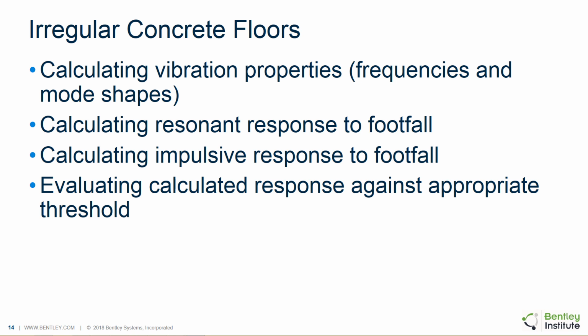And typically what we'll be wanting to do in our day-to-day vibration assessment is to calculate the initial vibration properties, which are the frequencies and mode shapes. We will want to calculate the resonant response to footfall, the impulsive response to footfall, and then evaluate those calculated responses against some appropriate threshold. So we'll take a look now at how we can do that using RAM Concept and accomplish all of this